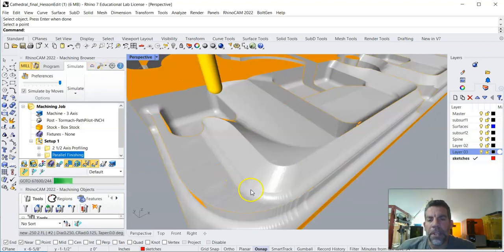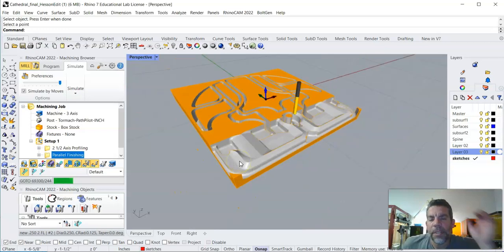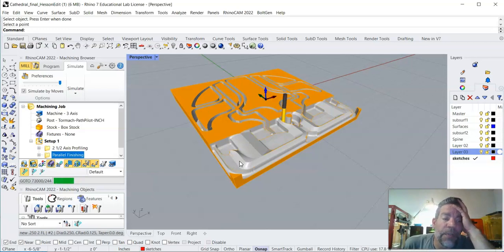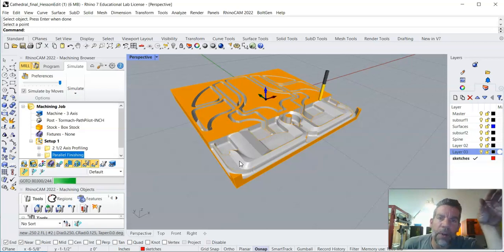Looks like we're getting a pretty decent fillet there too, and that's the type of stuff that I've gotten to where I'm starting to not model as much, because if I know how the end mill is going to hit a region, it's not worth the time of sitting there messing with fillets in Rhino if you understand what the CAM software does. And that's what I was telling you, even being particular about your Rhino modeling here in the beginning, if you actually understand the CAM and what it's doing, you can start to create textures by changing your step over, by changing the direction that you're running.